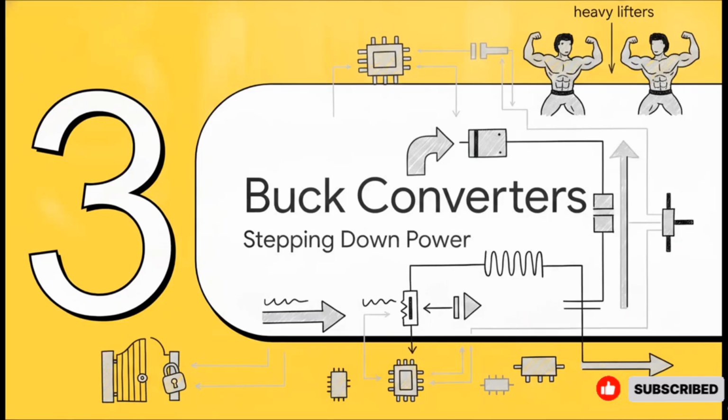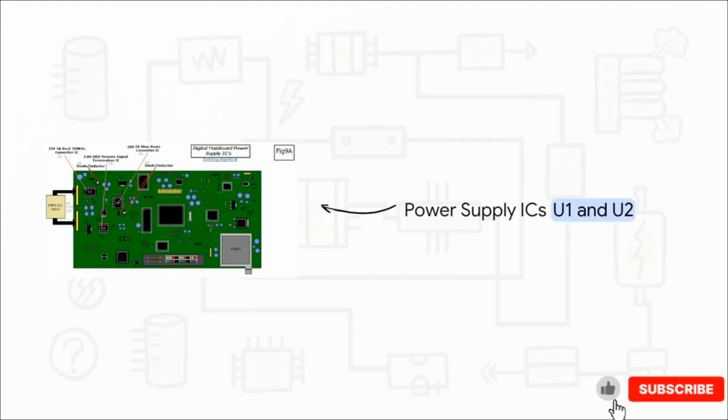Okay, on to section 3. Buck converters, stepping down power. Now, if the LDO is the gatekeeper, suspects 2 and 3 act as the absolute heavy lifters of the power board. Right on the main board, you've got U1, which is a 20-volt 3-amp buck converter, and right next to it, U2 is a 20-volt 2-amp step-down converter.